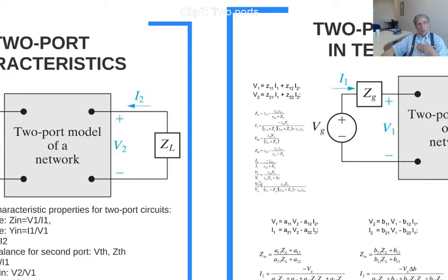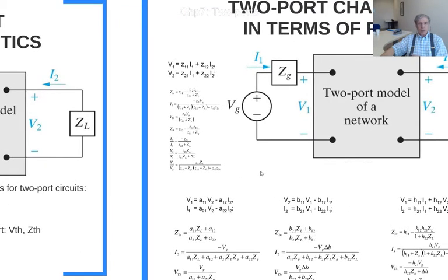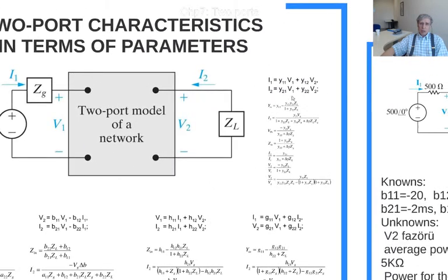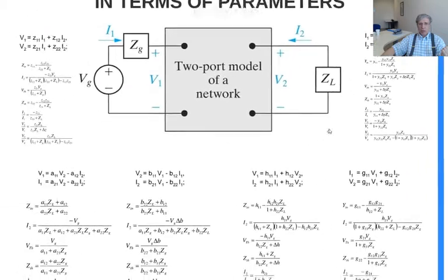Now we are saying that you can find these characteristics directly by using the Z parameters. So you could use this table. It is also available here, a table. If you know the Y parameters of this two-port circuit, the 6 parameters that we mentioned already can be calculated by using the Y parameters in here.